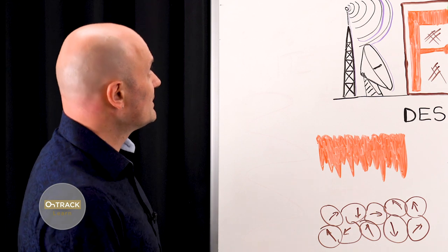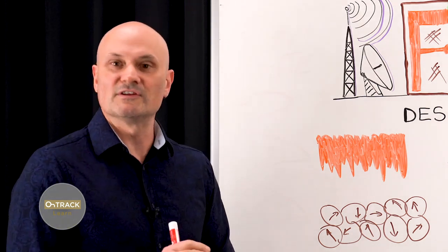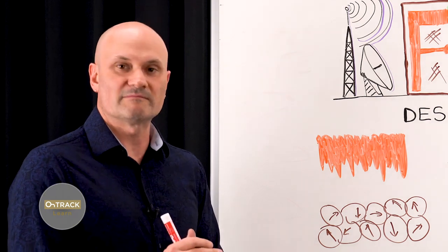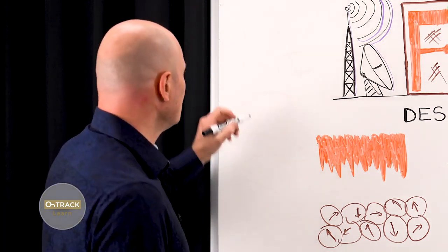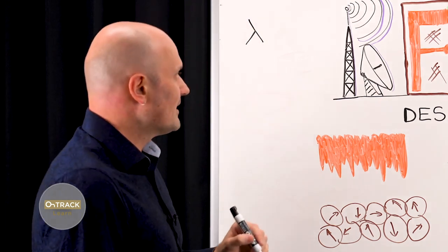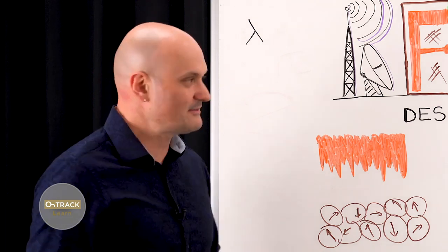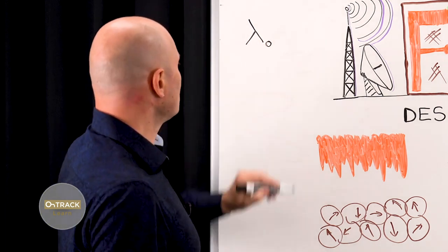And so at those frequencies, a few things behave differently. First of all, let's talk about the most important thing to know when you're dealing with different RF or microwave frequencies, and this is wavelength. If we're dealing with signals that propagate through the air from an antenna, for example, we're dealing with lambda 0.